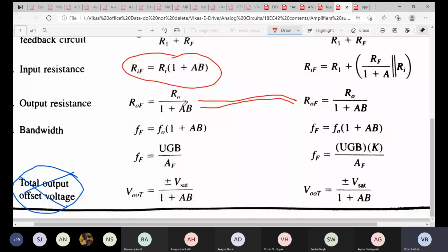So that's how the equation remains the same, and that's what I have given you as the small assignment, to derive that particular equation. And then I also said the bandwidth of my non-inverting amplifier, which is my voltage series feedback amplifier, which we derived earlier, and we understood the entire aspect of break frequency and bandwidth yesterday. The bandwidth was f0 times 1 plus A beta. So normally without feedback f0 will be my bandwidth. What is f0? On a gain-bandwidth graph, the particular point where there is a 3 dB dip is my f0. This is the particular frequency till which the gain is constant.